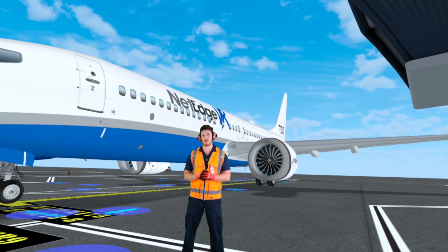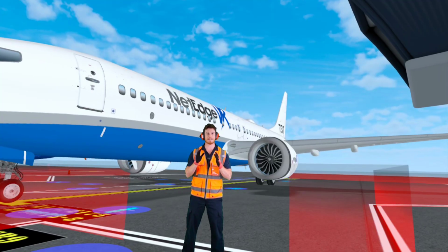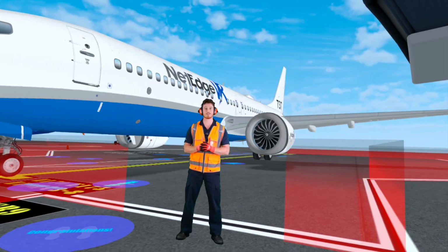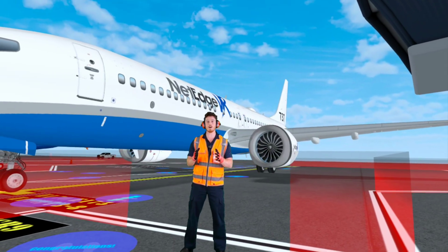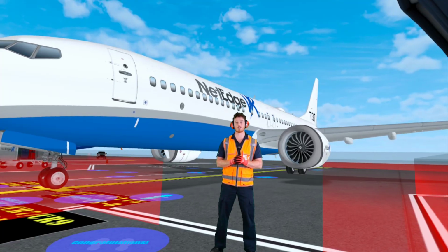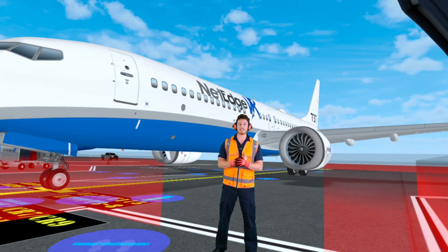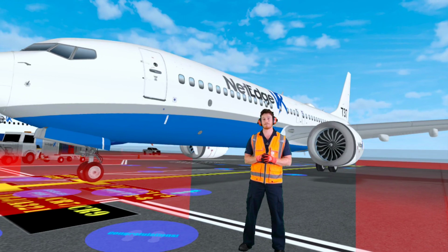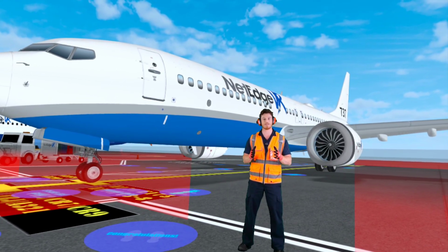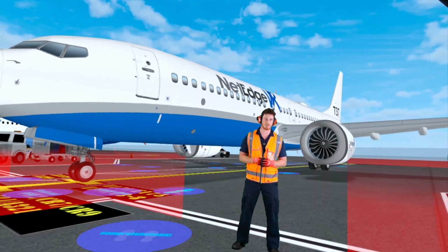In addition to the walk-around path, you should also be aware of the Equipment Restraint Area, or ERA, also known as the Circle of Safety. The ERA defines the area in which operators need to be extra alert and cautious. Ironically, most accidents will occur within this area, so it's important to stay aware of hazards and use extreme caution within these zones to maintain safe operations.